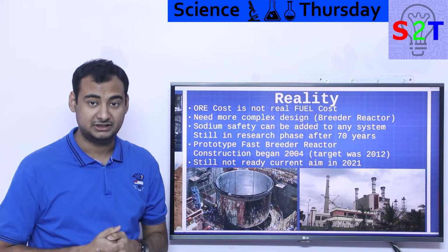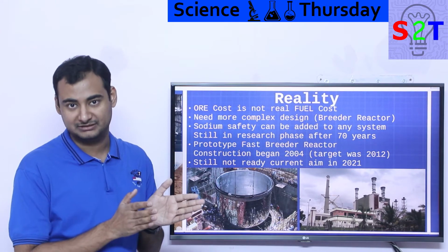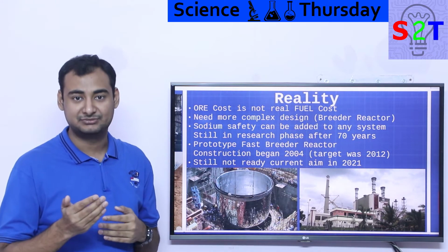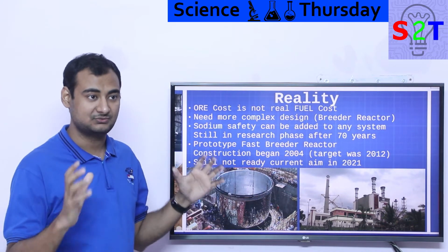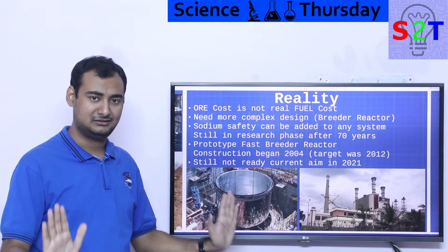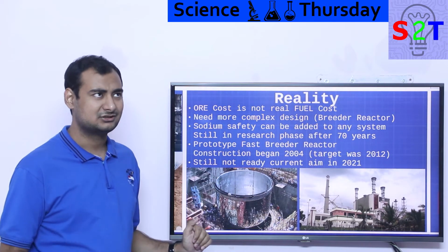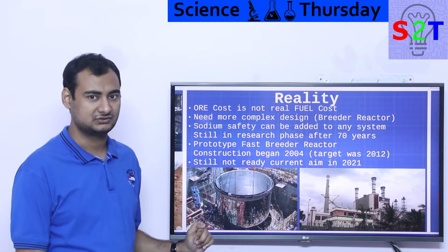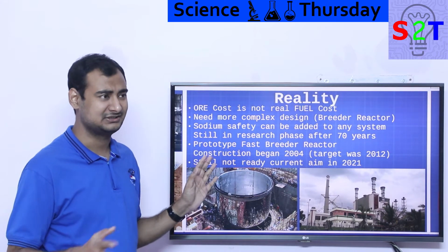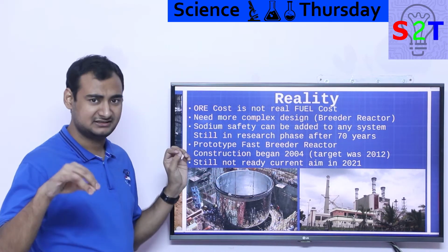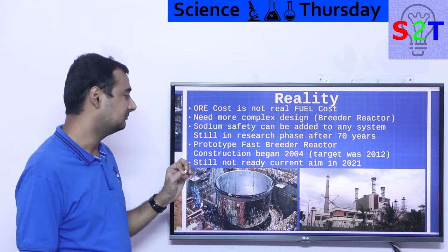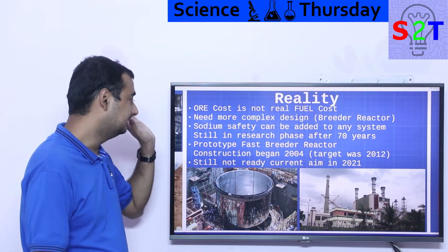So people want to use sodium. The benefit: sodium is solid at room temperature and liquid at very high temperature. So it will go to the same temperature as a liquid water system, but it will not have the pressure. So steel pipes are like, I've got this, I'm calm, I can handle that. The consequence of that is that it is ludicrously corrosive. But it can be managed. People have figured out some new alloy compounds that can handle that, and mixing some things with sodium itself will also make it less reactive, but it can be done.